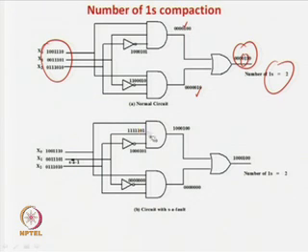You can just say that the pattern is all ones, because this one is connected to here, and it is a stuck-at-1 fault over here. And again you can see that this one is all ones, so it is all zeros over here, and if you compare the values and compute it, you can easily find out this will be a 1. Because this is stuck at 1, every bit will be a 1. So, there will be 2 instances of 1s here.